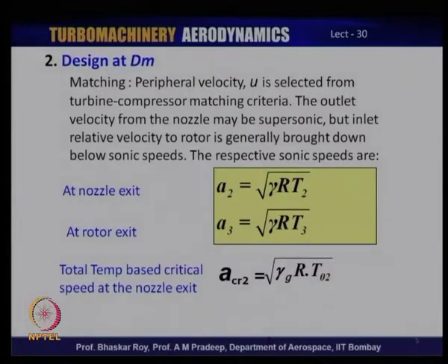We have seen that the LP turbine is often set at a higher radial station, essentially as we have discussed, to achieve a higher value of U. This is precisely the point that you may have to select the annular space and the RPM together to arrive at a value of U that matches with the compressor and supplies the work to be supplied to the compressor.